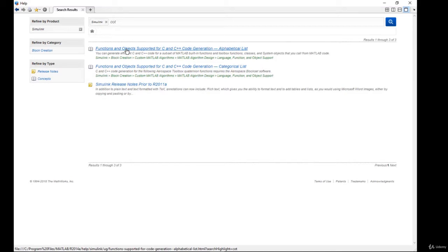It means that we don't have any block for simulation of cotangent x or t, so we should make it. In doing so, you must find its math equations or use a MATLAB function and define the code in it. I will explain it step by step later. So I close the help window.